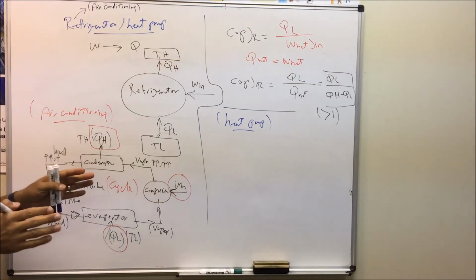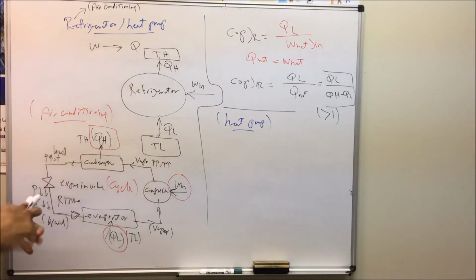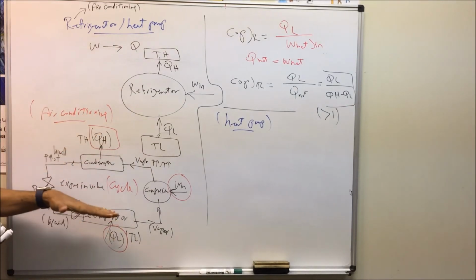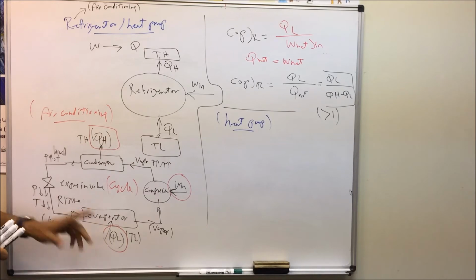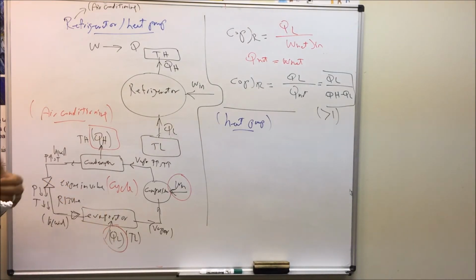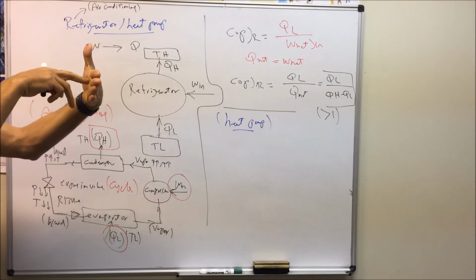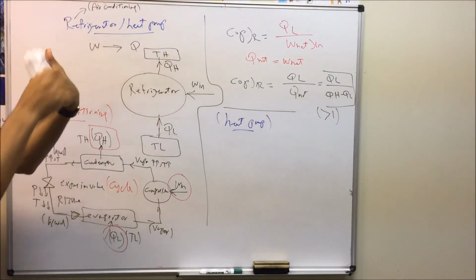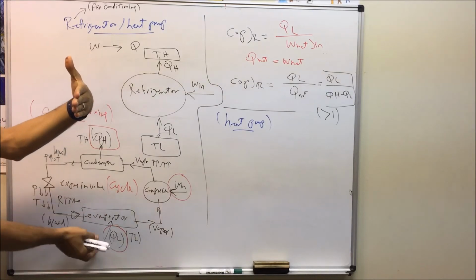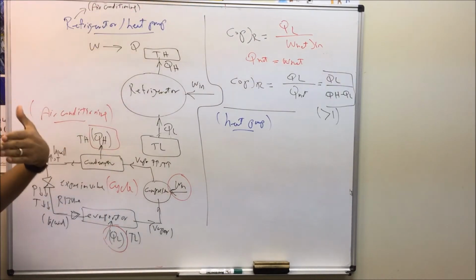So if you do have a split air conditioning system, we just put it in the wall. The inner part of the air conditioning system, inside your room, you will have what? The evaporator. So in this case it will absorb the heat from inside the room, and it is just fixed into the wall. The condenser in this case is outside the room. So we absorb the heat inside the room, Q low, take it and reject it outside.